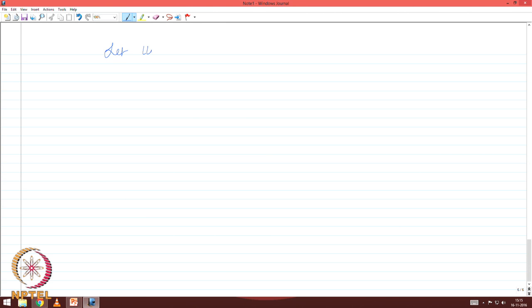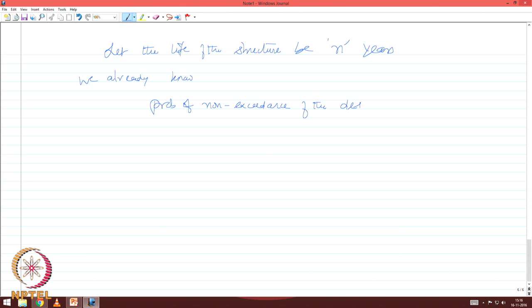Let the life of the structure be n years. We already know probability of non-exceedance of the design load in any one year is 1 minus 1 by r.